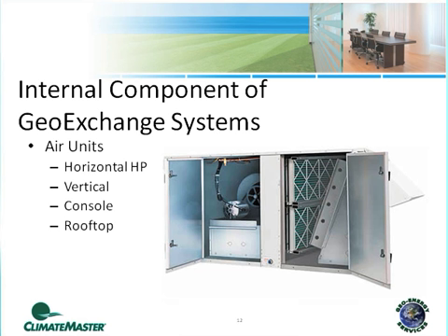Rooftops also have a good marketplace for retrofits. If you've got an existing packaged rooftop unit and you're looking to replace that unit, it's at the end of its life and needs to be replaced, you might consider replacing it with a rooftop ground source heat pump unit. These can handle all sorts of outdoor air temperature conditions. In fact, they can be designed to handle 100% outside air conditions and situations. That's a little bit more of a customized unit, but it is possible to make those types of units.